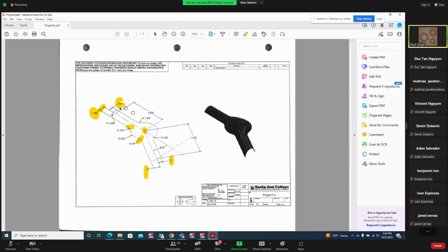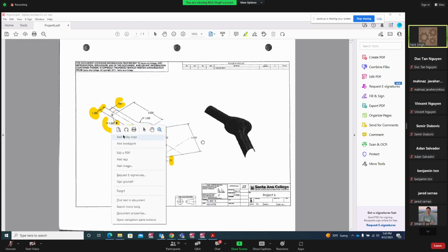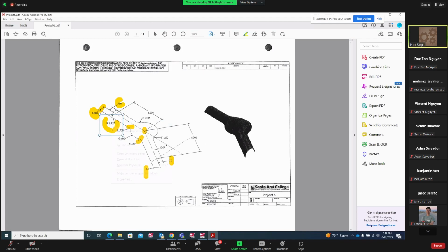All right, now we have to do this arc over here, radius 1 inch arc, this guy right there. So how can we create that arc? We have to go to construction plane. This was my top plane. This is my right plane. And the right plane, what's going to be my Z minus 6 inches from 0. So let's go to construction plane right, and we're going to create this 1 inch radius arc. This is the start point, this is the end point right there, and radius is 1 inch.